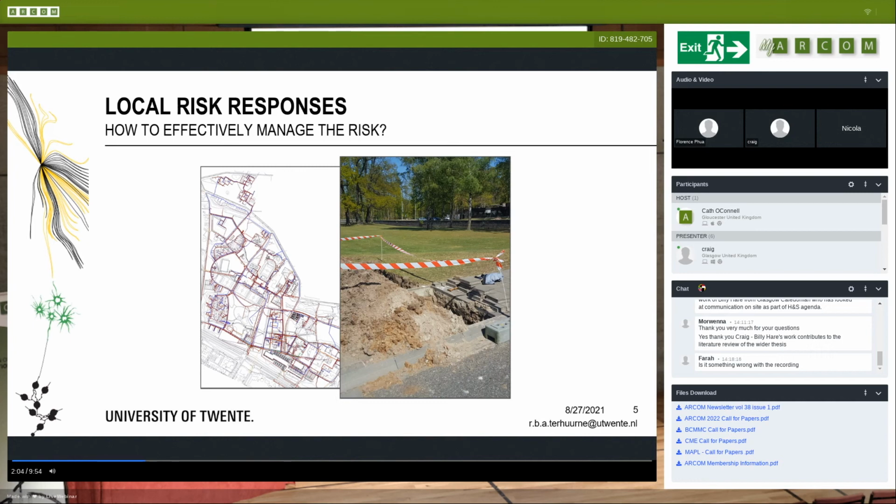This means an understanding is required about the involved risks at the construction site to make a conscious decision on where to locate the specific trial trench. The complexity of the buried utilities in combination with the uncertainty about their whereabouts makes utility locating, and therefore effectively managing the risk on excavation damages as well, a highly challenging task.